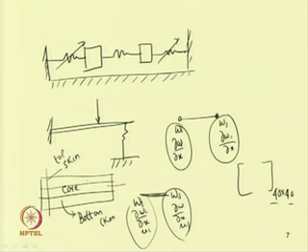Similarly, in the case of the flexible core sandwich beam, the top and bottom skin deflections will be different. So at the ith node one can have W_t, W_b, theta_t, theta_b and u.